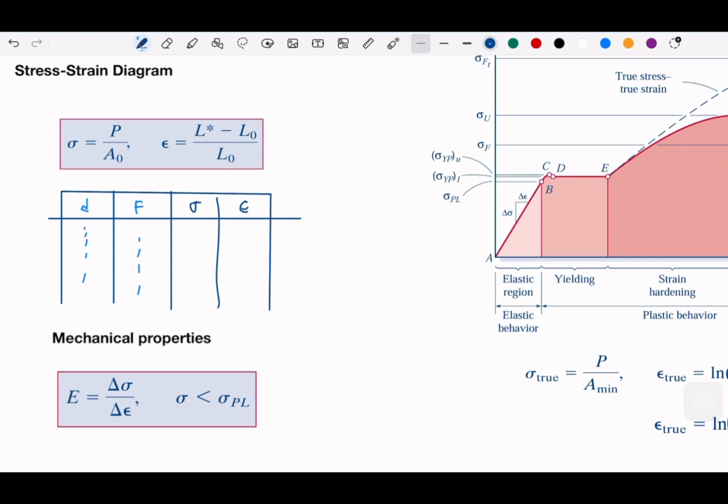We have a new strain, we have a new stress, because in every period of time, of course, the forces will be different. And this is what we expect. So when we take our time pulling the steel, we get this line, which is expected until some part on this curve, which is not going to be a straight line. It is a little bit bent here, and then a little bit getting to a horizontal line.